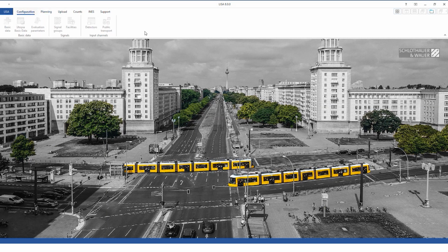So you find tools for the configuration of the intersection, meaning everything that is hardware out there that you want to configure, like the topology of the intersection, signal groups, and so on, detectors, public transport, detection chains, and stuff like that. Then there's the planning part where you do the calculation of time parameters and defining offsets and so on, defining stages, stage transitions, signal timing plans, and time switch or the automated timetable.